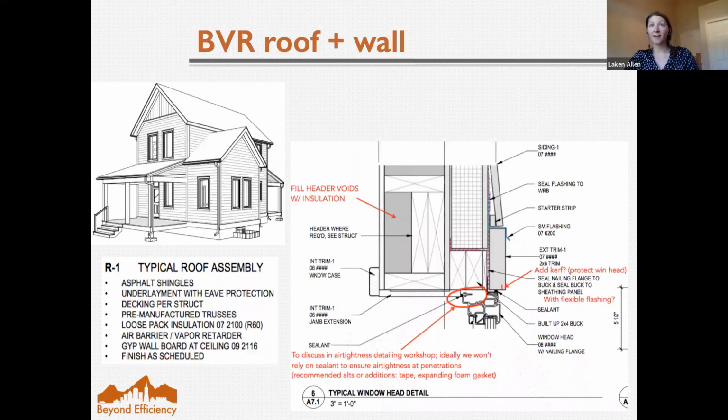And then I do have one window question from Michael Best. Do you ever mix the specs on the windows based on wall elevation and other considerations? So the question is sort of tuning windows by facade. I think there are definitely situations where that makes sense. You do run the risk of window orders getting messed up, or a window getting installed on the wrong facade if it's otherwise the same rough opening size. But that's a problem that can be solved. And I think tuning windows actually can be very effective.